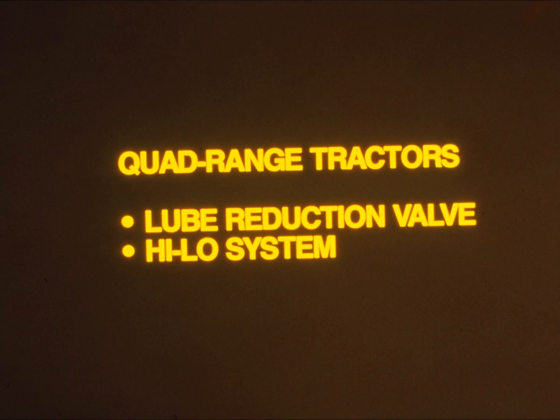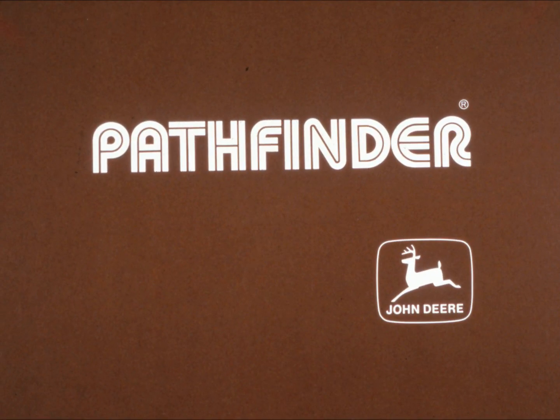If you were diagnosing a tractor with quad-range transmission, the diagnostic procedure would give you tests to check for lube reduction valve function and to check the high-low system for leakage. Next, go to step 32 and press the restart button.